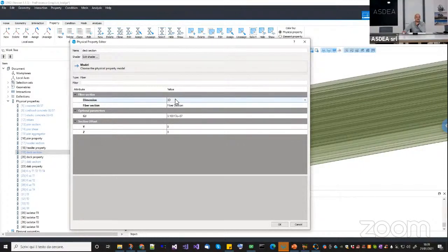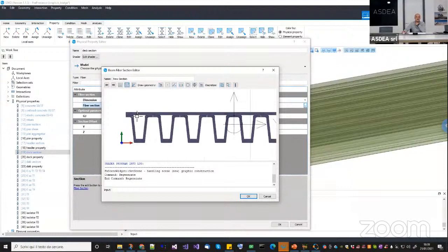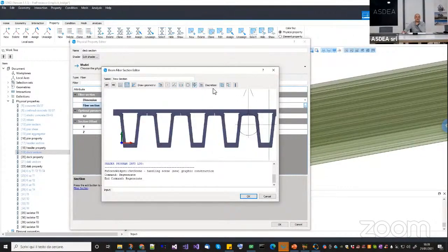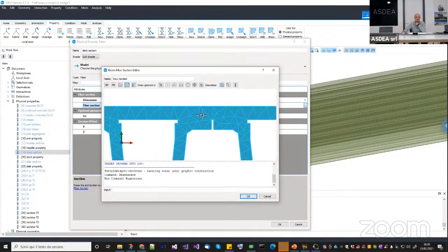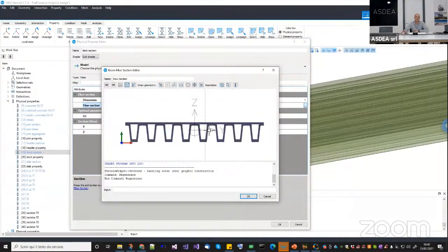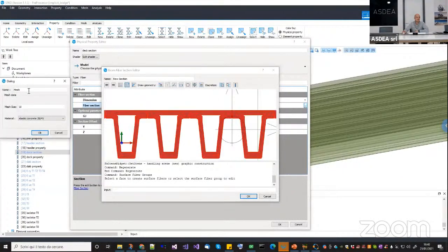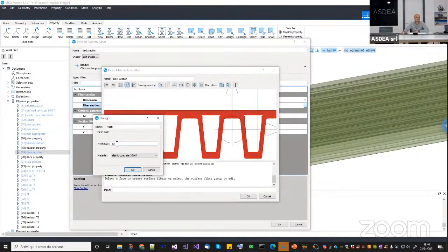So basically here you decide the dimension, we are in 3D. Here you can open the fiber cross section editor, okay? And basically here you have some CAD commands to draw your shape, and then you can mesh it. Now the mesh is not extremely fine because it is elastic. I mean, I don't need a very fine mesh. And all the things here have a mesh of pretty much 10, and the material is the elastic concrete, as you can see.